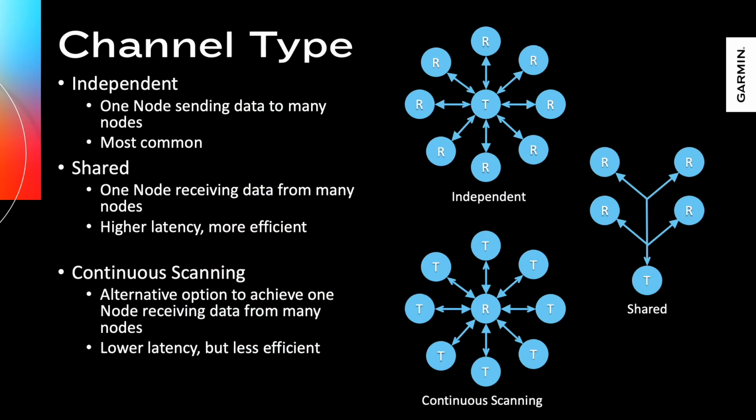So far, we have covered how a channel can be thought of as a data pipe that connects two nodes together and is open periodically. But what differentiates one channel from another? If there are many devices in a room, how does a wearable that displays heart rate data know it is connecting to a heart rate sensor and not a cadence sensor? How does the wearable differentiate between two different heart rate sensors in the same room? ANT channel parameters solve these problems and more.